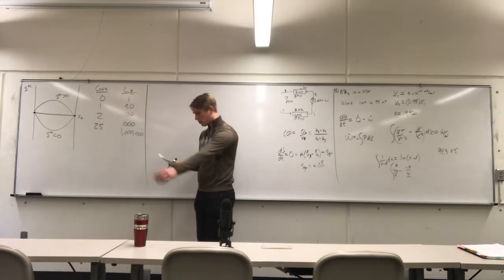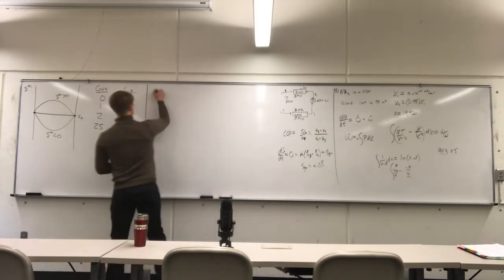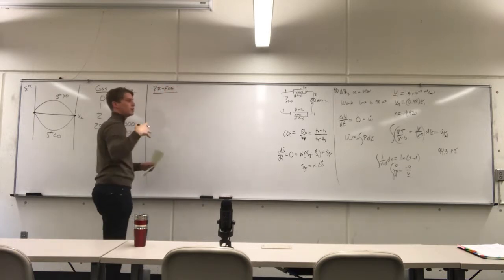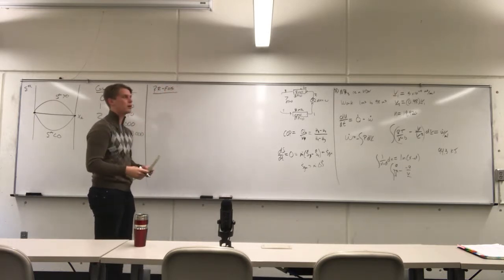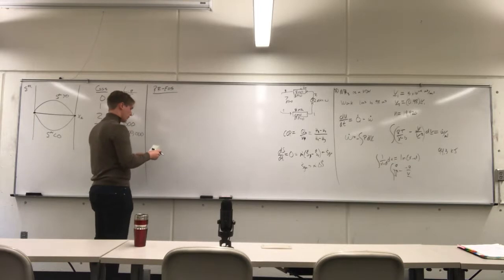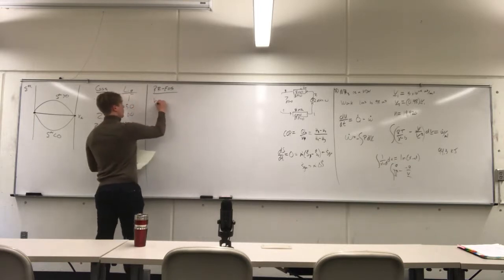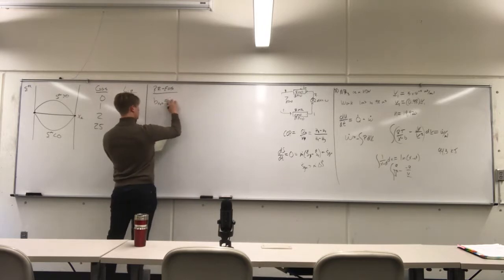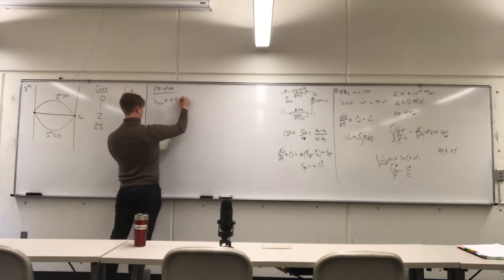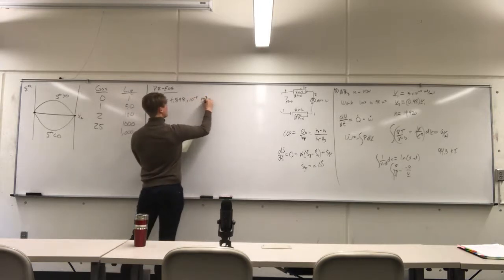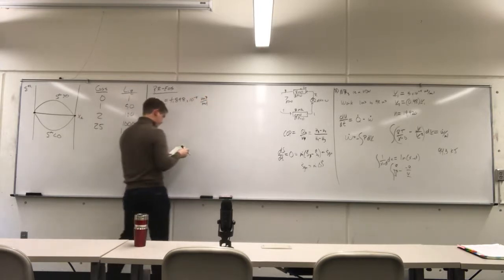So I've already explained the goal. The Peng-Robinson equation of state is what I used to estimate the specific volume of water. I guess I should have looked up the real density of water, it would be better. But anyway, I used the Peng-Robinson equation of state to do all of this. The excluded volume of water, according to the Peng-Robinson equation of state, is 1.898 times 10 to the minus 5 meters cubed per mole.